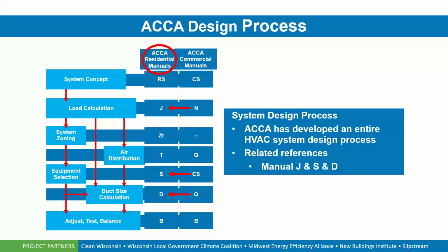That's a duct system design size that includes all supply and return ducts and registers based on Manual J and the Manual T. And that Manual T is entitled Air Distribution Basics for Residential and Small Commercial Buildings, as it pertains to supply outlets, return inlets, registers, and grills, for instance. So using all of these in conjunction, we can get a properly designed system, which will lead to a system being properly balanced and increased comfort for the occupants, hopefully decreased energy costs, as well as prolonging and extending the life of that HVAC equipment that's been installed.